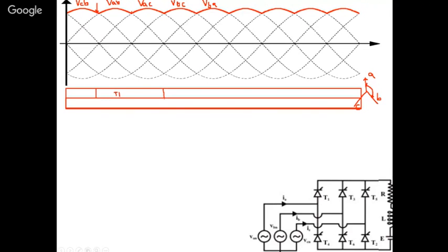A phase is more positive in the sense A has more voltage and the other two are a little less. So when the A is more, the thyristor which is connected to that A will also be forward biased. Okay, so similarly here, say when the T1 is connected to this A phase, so you can see here until this A is not less, that is A is more positive here, T1 will be on. After that, after 60 degrees, T2 will be on.